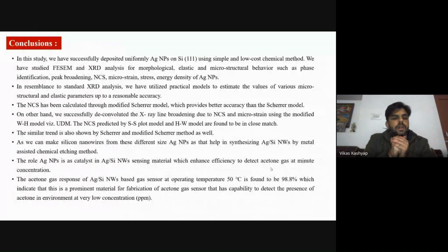From this, the conclusion of my talk is that in this study, we have successfully deposited uniform Ag nanoparticles on silicon using a simple and low-cost chemical method. We have studied FESEM and XRD analysis for morphological, elastic, and microstructural behavior such as phase identification, peak broadening, NCS, microstrain, stress, and energy density of Ag nanoparticles. In addition to standard XRD analysis, we have utilized practical models to estimate the values of various microstructural and elastic parameters up to reasonable accuracy.